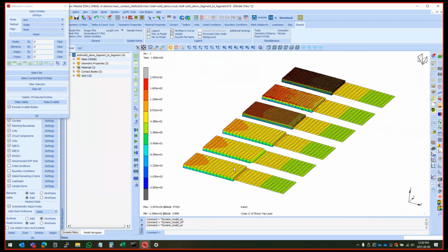So as I load it down, there's a tensile stress at the top, which means due to Poisson, it shrinks at the top in this direction. At the bottom, it compresses, but it expands. And that caused that section to actually form some kind of a bow section.